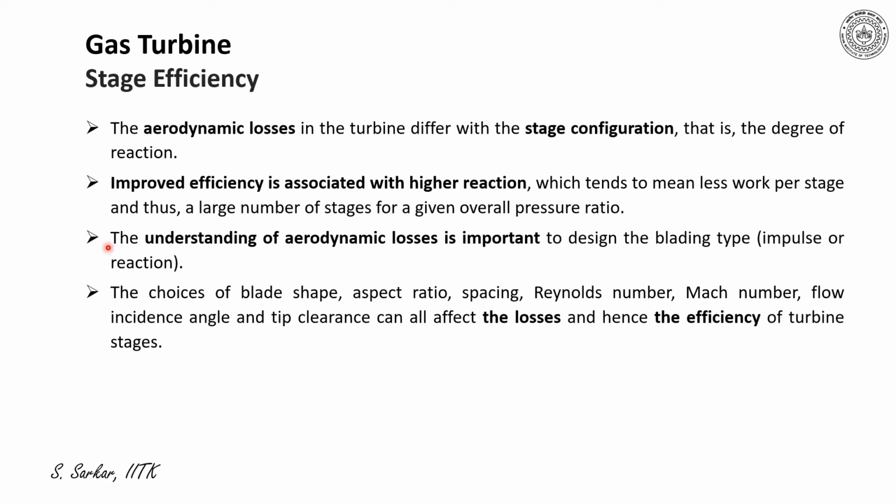Thus, the understanding of aerodynamic losses is important to design the blading type, that is, whether one should use an impulse or a reaction stage for a particular application.